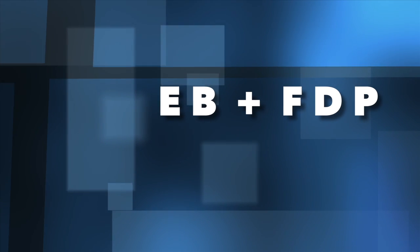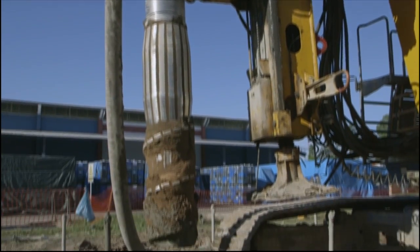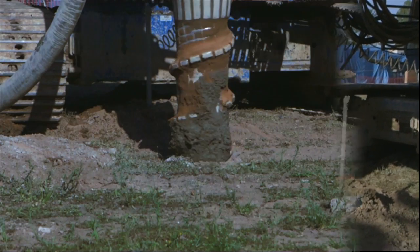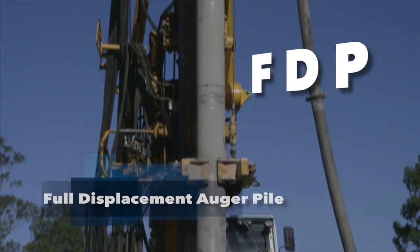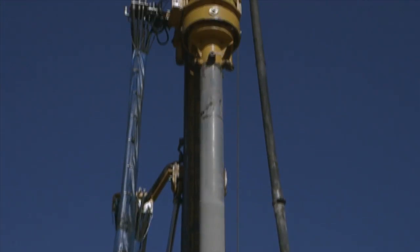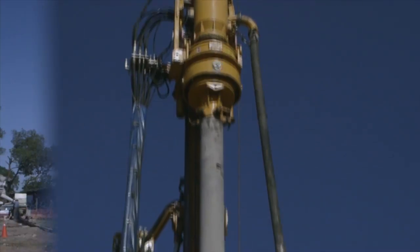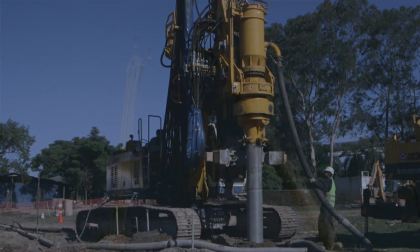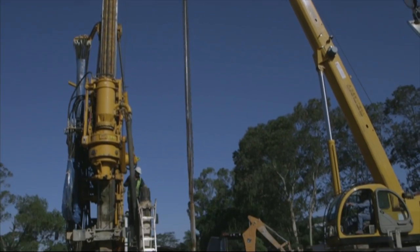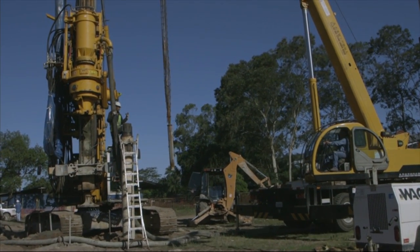EB plus FDP. An important improvement of the auger pile method was the introduction of a specially designed displacement auger, the full displacement auger pile, FDP, with a specially designed drilling tool, which during penetration displaces the soil laterally. Another important advantage of the FDP method compared to conventional bored and auger piles is that the installation process can be monitored and documented in great detail.